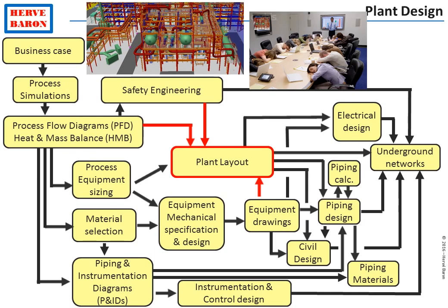Once some information, at least preliminary information from equipment is available, it's possible to nail down the plant layout, which is another essential step for virtually all engineering disciplines to proceed with their work. This is done with the client during the first, also called 30%, plant model review, which is done in 3D.